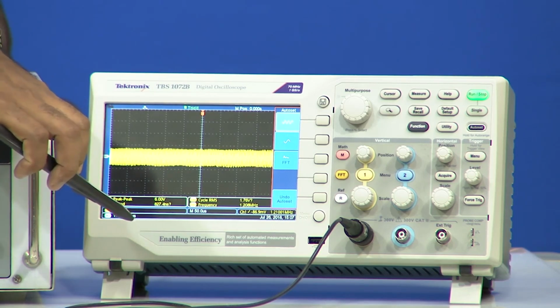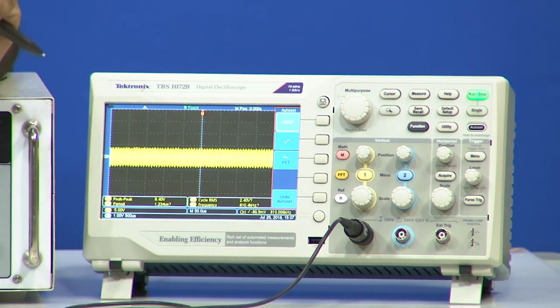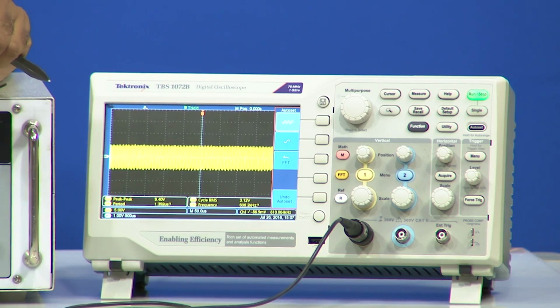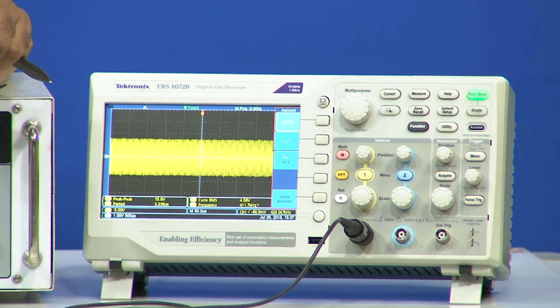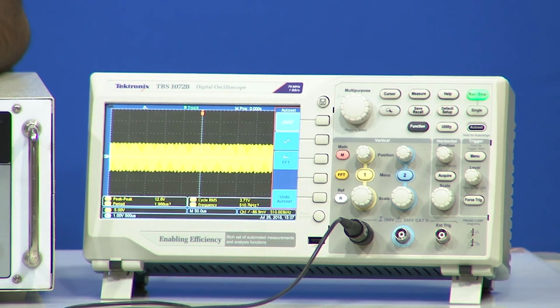So we can see that if you put a very hard constraint, then you are getting the 16 volt peak to peak output only till around 300 to 400 kilohertz, maximum around 400 kilohertz. Even at 500 kilohertz, you are getting only 13 volt peak to peak, which is what we are seeing here. So you understood, right? Our gain is 2.2.